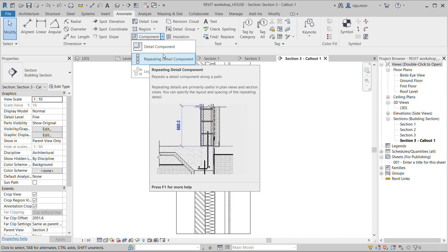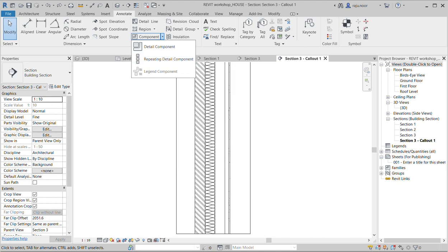So for example, brick mortar joints are a repeating element within a wall. Therefore, you would draw it and it will draw it at the right centers, at the right height, at the right distances, as you draw your line. So you don't have to work out distances and that kind of stuff. It will work out because it's set to put in the actual component at the specified centers within the actual properties of that component.